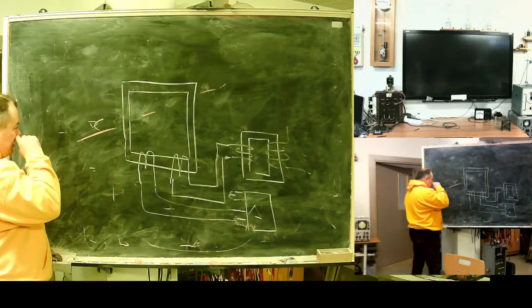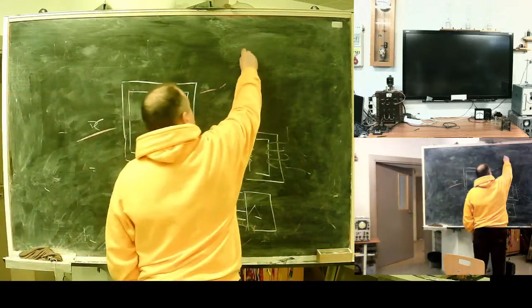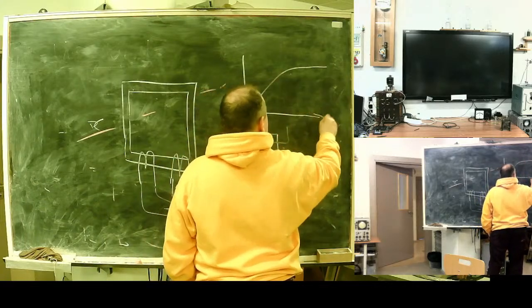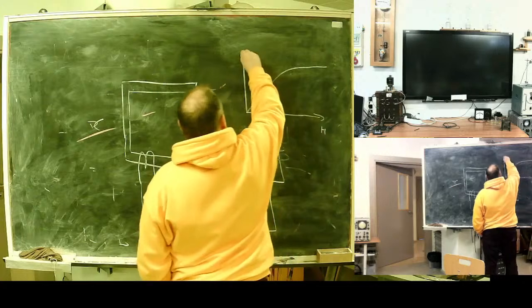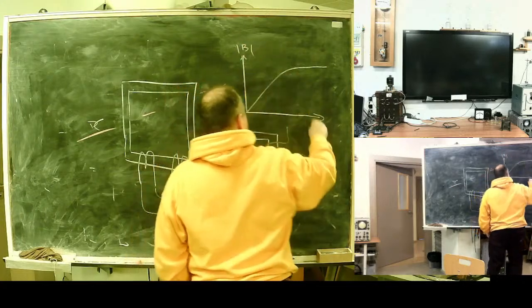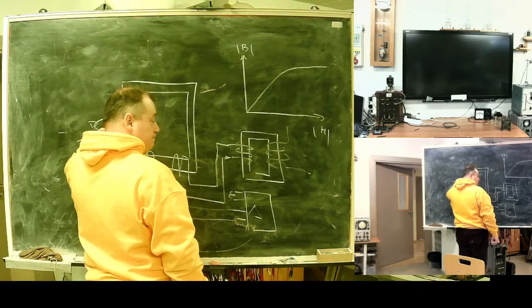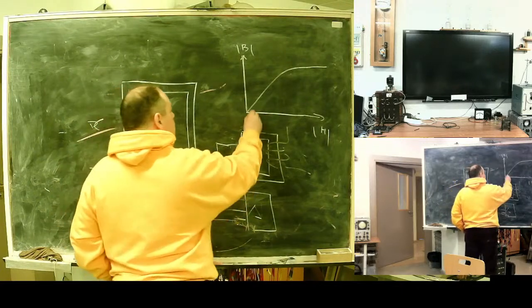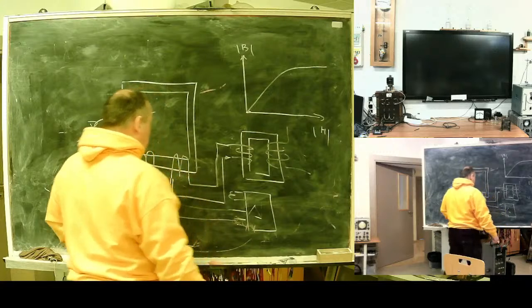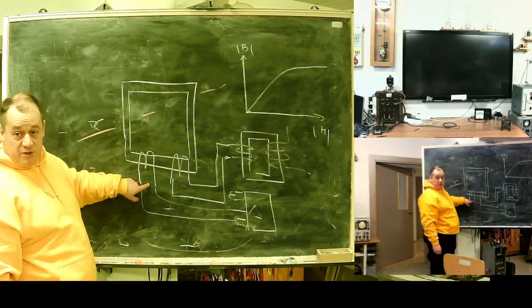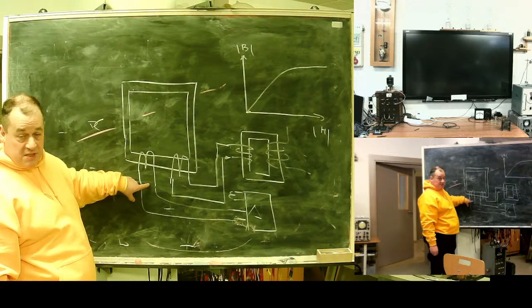The idea, again, is usage of the saturation curve. Without a DC component, you would be somewhere here, and current from the auxiliary coil transforms to this coil without any disturbance.